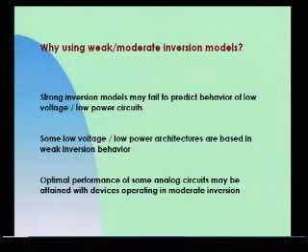If there's any doubt why use weak or moderate inversion models, let's also mention that if you try to design a circuit using a strong inversion model, but your circuit will operate with low voltage or low power, and so your devices will be in weak or moderate inversion, we will fail to predict the performance of the circuit properly.